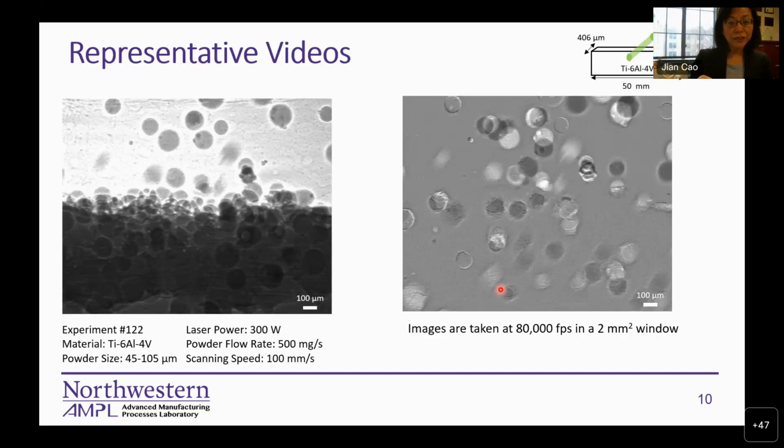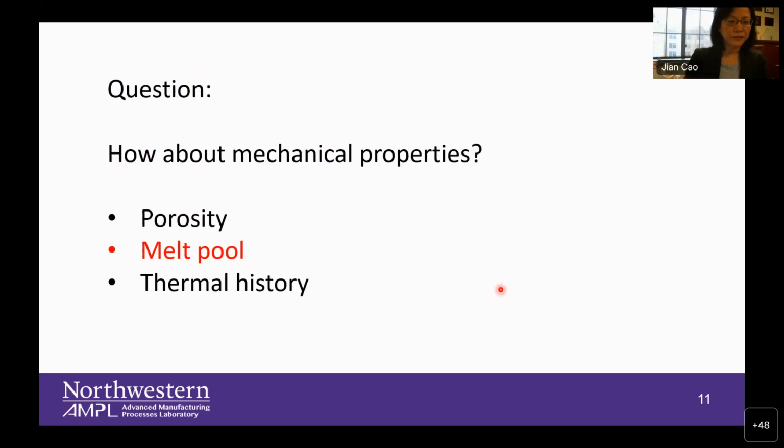And specifically, we found out for our particular application with the DED, you are carrying a lot of gas into the melt pool. So the melt pool depth, in addition to the width and the length that powder bed people typically look at, for DED the depth is actually equally important. So because of that, from the numerical point of view as well as the practical point of view, we say, okay, how can we control the melt pool depth during the buildup?